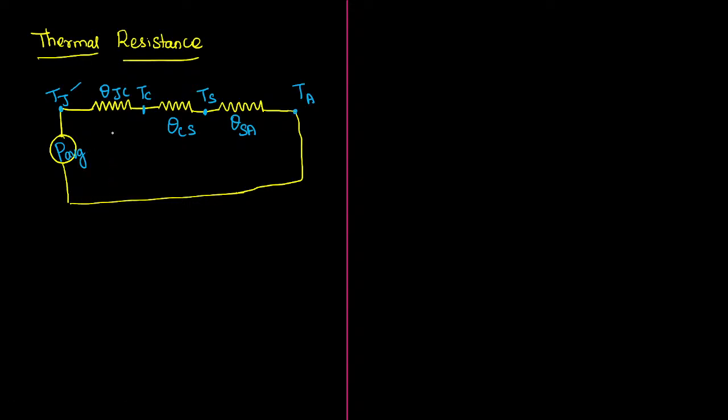Okay, just to remember: how do we define this average heat? You can relate this with the current in the electrical domain. You can relate this temperature with the voltage. You can relate this theta with the resistor. Let me define it. According to Ohm's law, how will you define current I?